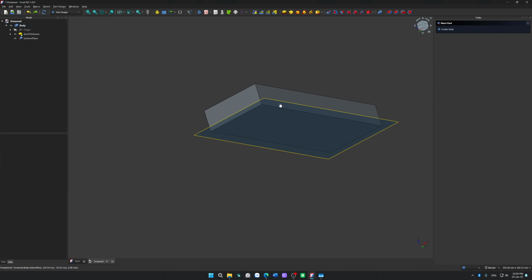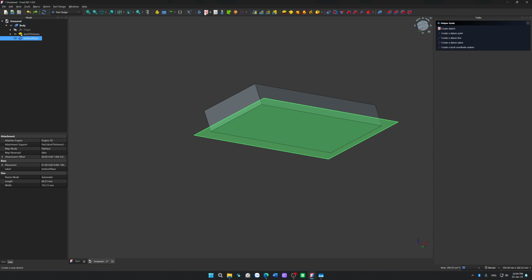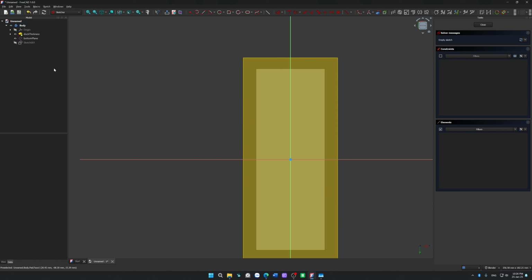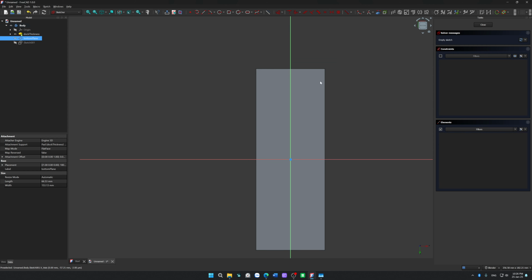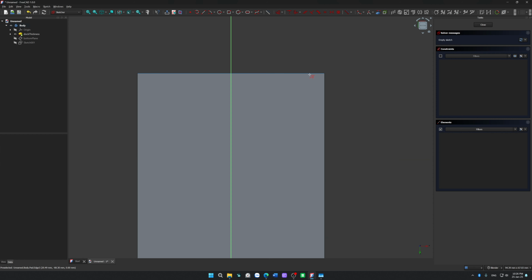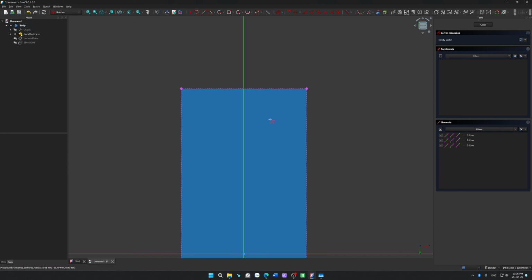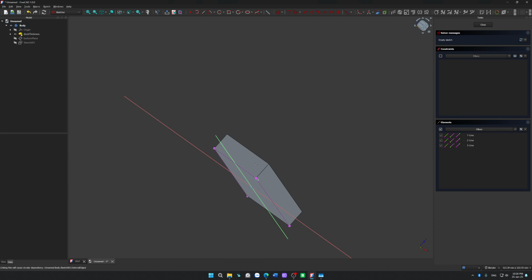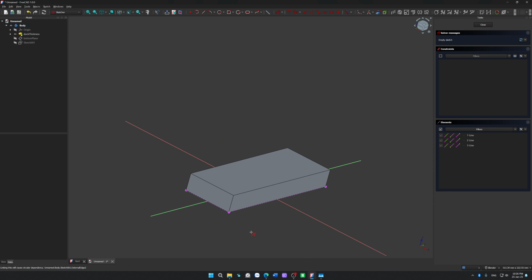You have to select this first and then create a sketch. Now toggle the visibility and create some external geometry. So we will reference this side. This is bottom, right? And wait, this is the bottom, so it will go in this way.